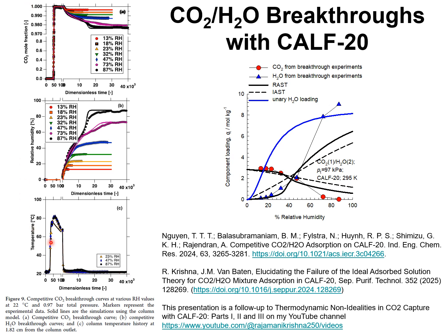On the basis of the experimental data, the component loadings in the adsorbed phase can be determined from a component mass balance, and these have been plotted. And the previous presentations have examined in detail why the experimental data on the component loadings do not conform with the ideal adsorbed solution theory for mixture adsorption equilibrium.